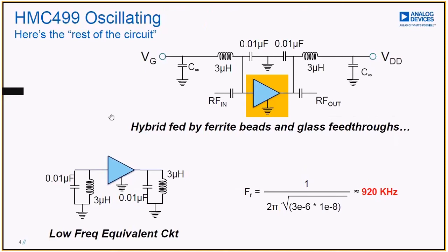And this is very typical. Amplifiers are often unhappy if you hang high Q circuits on the input or output. Different amplifiers have different sensitivities, but generally speaking, if you see an equivalent circuit that looks like this, you've probably designed an oscillator, not an amplifier.